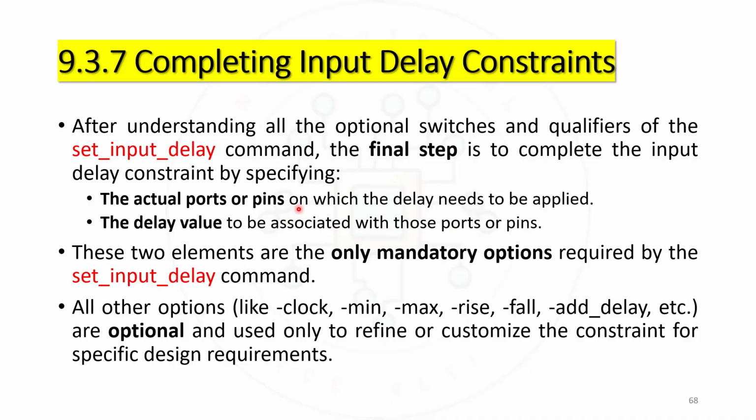So these are the two important switches. Generally, if there is any clock, we have to use hyphen clock followed by the clock name and the delay value, and we need to mention exactly at which port or pin we are applying it. And sometimes hyphen clock followed by clock name is also optional. Suppose you are not sure what clock is triggering the block which is present outside our block, I told you there is a concept called a virtual clock. We need to go with that, and that is also optional sometimes.